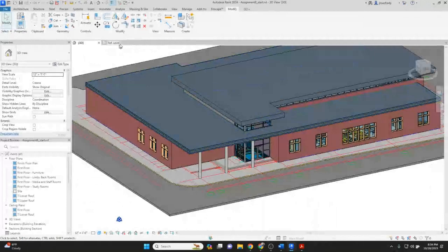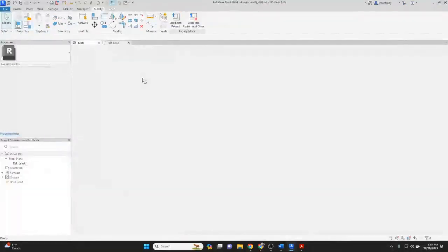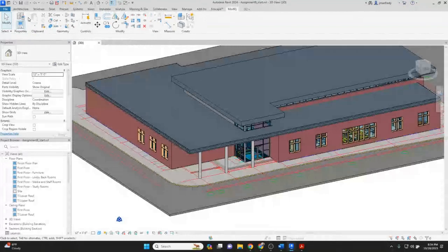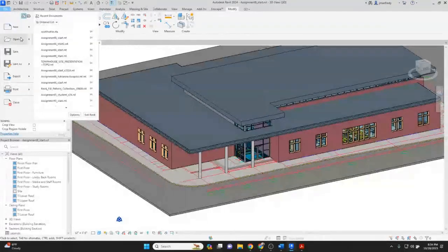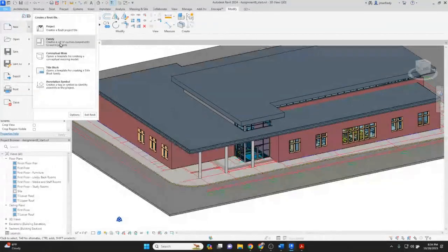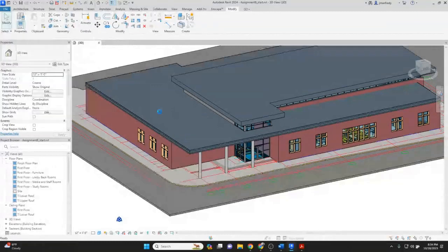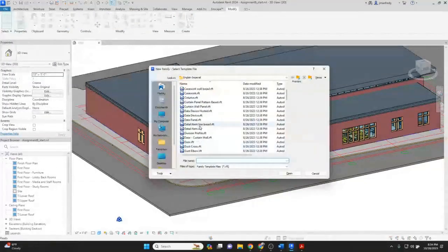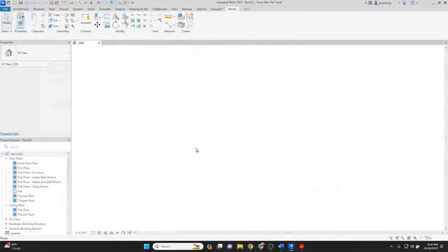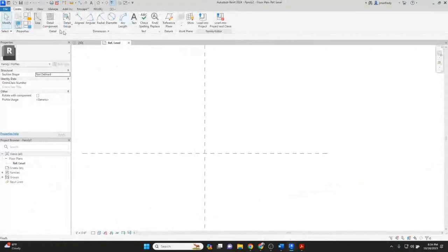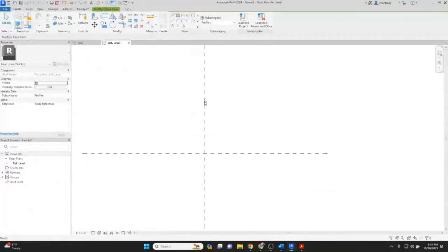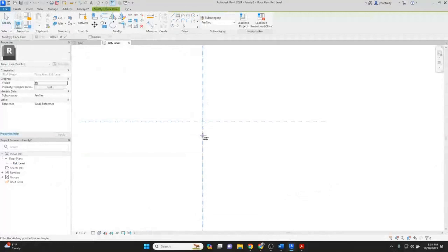I'm going to close this profile here. I'm going to make a new family profile for the sake of the elevations. New family. It's called a profile family. It's right here. Profile family. Open. And I'm going to draw that detail. So here I'll go line command, and you can draw it in any quadrant you want. You'll see the results when you place it in the model.